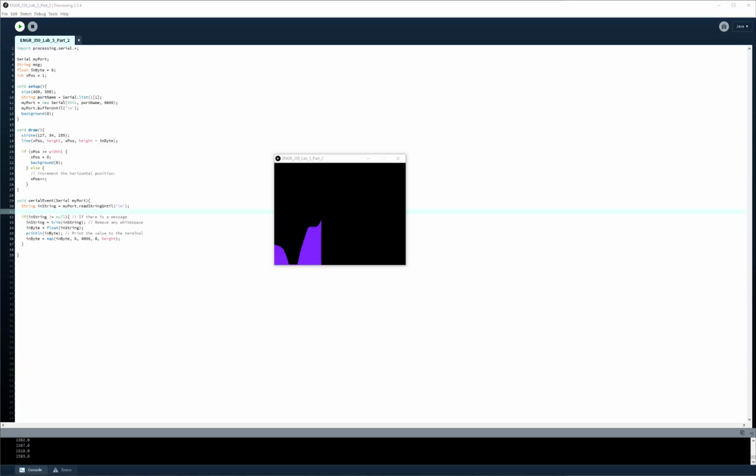Once you finish this section, you should be able to run the program on the Launchpad and the Processing application will plot the data. If it is working correctly, you should see something like I have here. Feel free to play with the different colors and other parameters. You may also notice the potentiometer can be quite noisy, which is quite common for real-world electronics. This usually has to be considered when designing products, as filtering can be quite important.